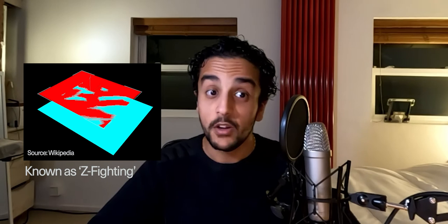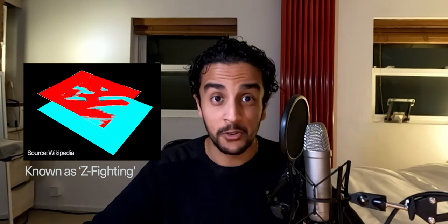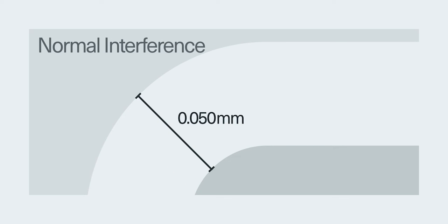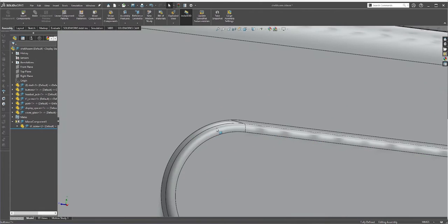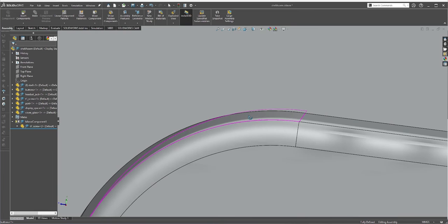The reason for this is because two coincident polygons or faces create a confusing surface for the Redshift engine to work with, especially if they've got different materials applied. As a rule of thumb, I try to aim for at least 1/100th of a millimeter interference gap between parts, although this is usually closer to 5/100ths. Keep in mind, this is for the small models. Larger scale models might work fine with larger interference tolerances. In this model, most things are tolerant to within 5/100ths of a millimeter, sometimes going down to 2/100ths of a millimeter, but never really less than that.